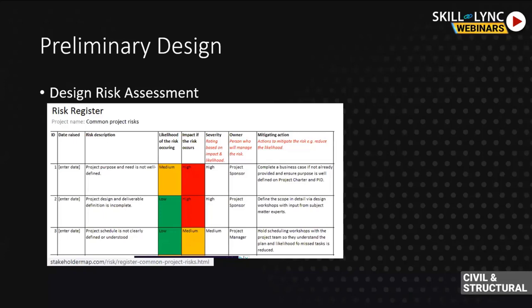But you have to define it right at the start of your project in the preliminary design so that it is accounted for. One very common risk is, say, falling from height. People will be working at height. Your bridge is higher, your lift shaft is higher. Anything beyond 3 meters is a dangerous height to fall from. And how do you mitigate it?